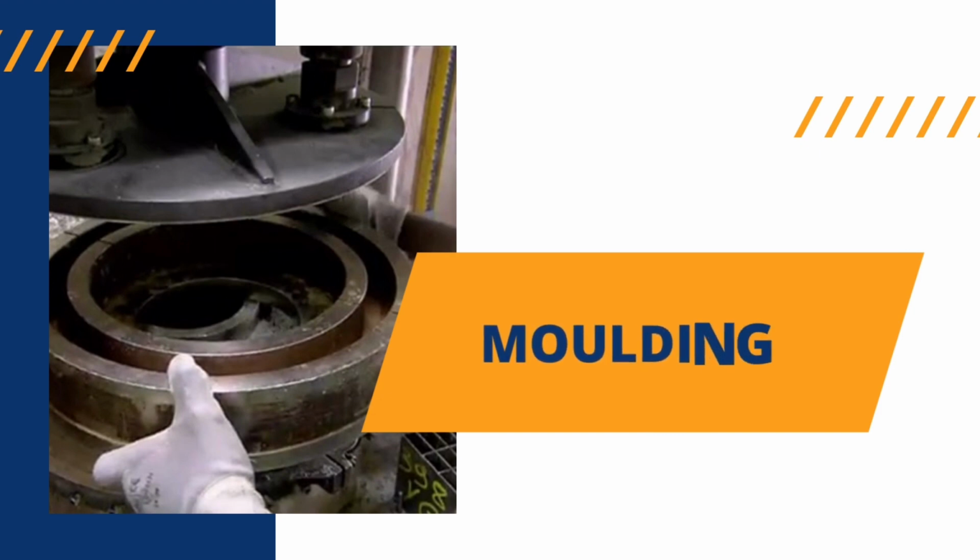The second step is molding. The ingredients are mixed together in a proprietary formulation and then loaded into a steel mold. Removable cores are fitted to provide the radial vents necessary to expedite heat rejection during brake applications. The mold halves are closed, and pressure and heat are applied. When the molding dies are opened and the cores are extracted, a near-net shaped brake rotor emerges.